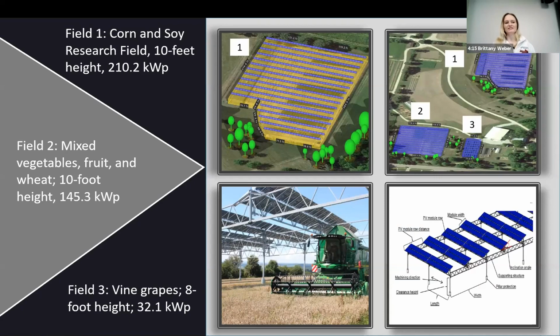An agrivoltaic system is shared land space between active agricultural production and photovoltaic modules. It's a relatively new system. All the studies that we looked at for our design encourage further research. Therefore, our agrivoltaic system is intended to be researched by students and faculty involved in the campus farm. Each system is set to be spaced apart so that the density of the solar panels is only 15% of the total land area. This ensures that the crops beneath will get the other 85% of the solar access.